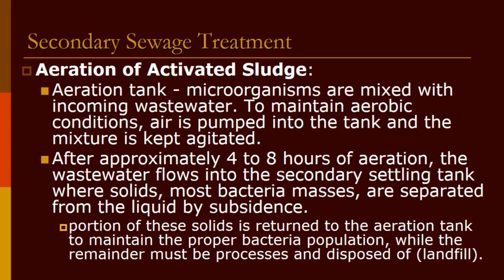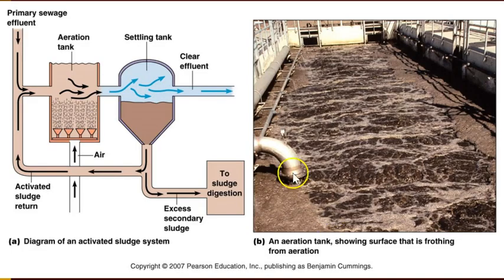And so the wastewater will flow through these tanks and let the bacteria and stuff do their work, and then anything that's solid, including bacteria and dead bacteria, are going to settle in your second round of sedimentation, and it looks something like this. It's lovely, isn't it? But you can see all of that air being bubbled through there. So here's your aeration tank.